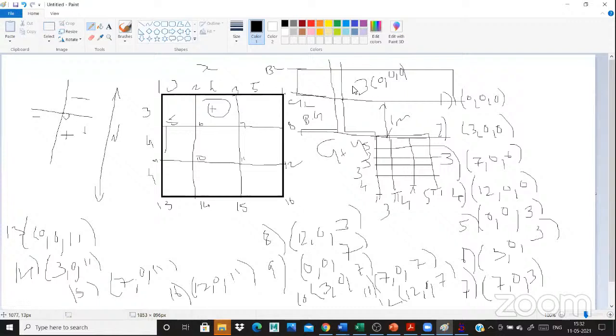This is 3 meter. Totally, my height is 4 meter. Sorry, this is 1 meter, means the basement is also 0.2 meter or something. Totally 4.2 meters. Or the depth of footing below the ground level is 1 meter. Our basement height is 0.2 meter. Our ground floor is 3 meter. Totally 4.2 meters. Okay.